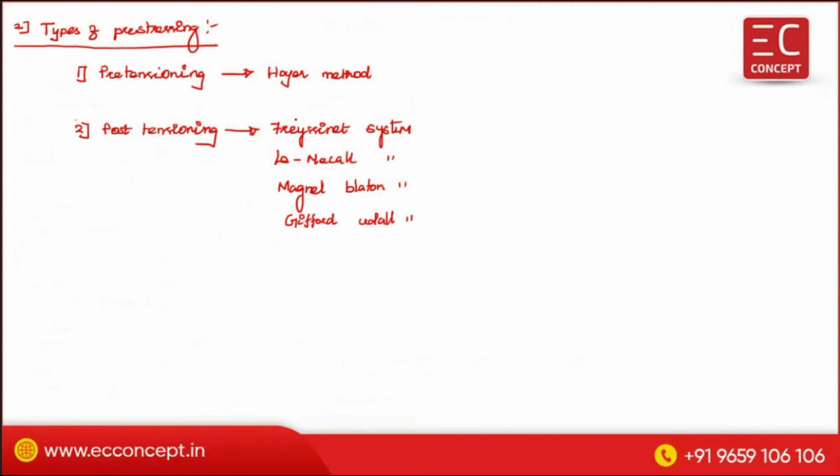So they will ask you in the examination which one of the following is the post-tensioning method or pre-tensioning method. This is very important for state and central government examination questions. You have to keep the Hoyer method in mind. Only one method is available for pre-tensioning and the other four are for post-tensioning.